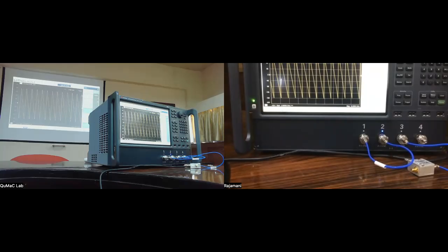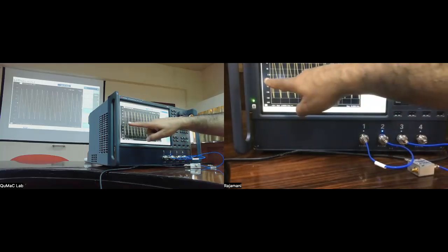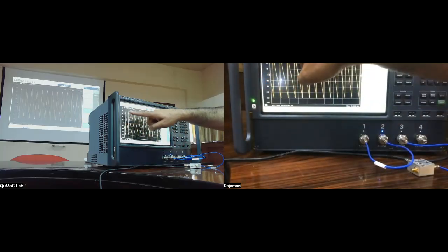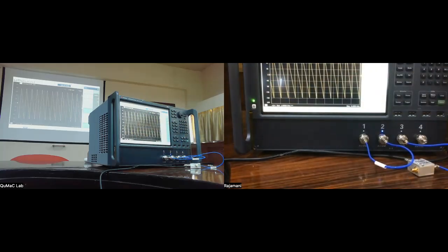And you see that the phase is running from some value and it keeps decreasing and then it jumps back. So this jumping back is just the fact that you're restricting the phase measurement between plus and minus 180 degrees. So total 360 degrees. That's the standard reference. There are probably some measurements here in microwave office also. I think I mentioned that there's this unwrap phase thing, which allows you to keep it in the same direction. But that's what is going on here.